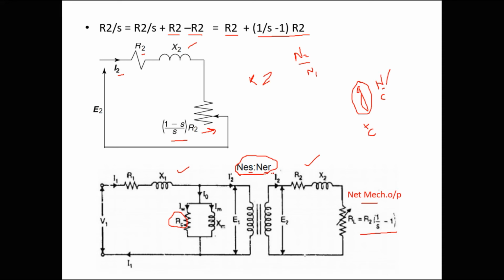Why do we call that effective? We know the EMF induced in any AC circuit is 4.44 times frequency, flux and the number of turns. And here, especially in a rotating machine, we have to consider the winding factor also, because of the arrangement of the winding on the core, so we have an extra term called winding factor on both the rotor as well as the stator.